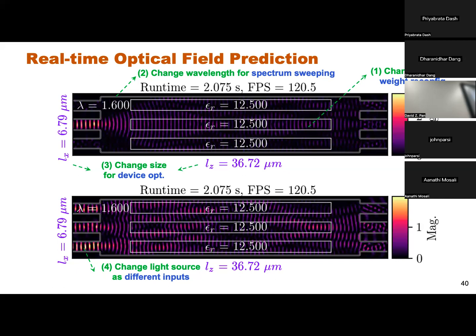Think about it. When you tape out your chip, you do VLSI design, you have a bunch of rectangles, and you send it to the fab. When the fabs get those rectangles, they say, okay, you followed my design rule, your job is done. But the fabs really have to make a huge massage of this mask you got from the designers. For example, they say this rectangle and this rectangle cannot be printed, or make this part a little bit fatter. They play all kinds of tricks, so-called mask synthesis, OPC, optical proximity correction.